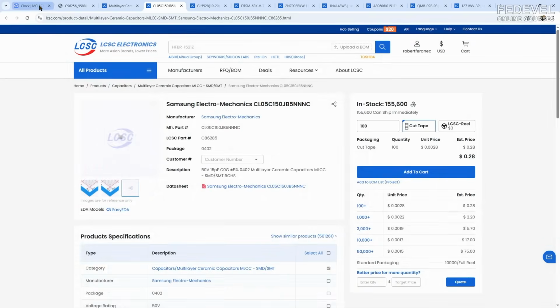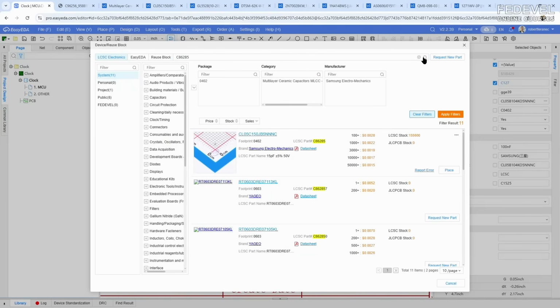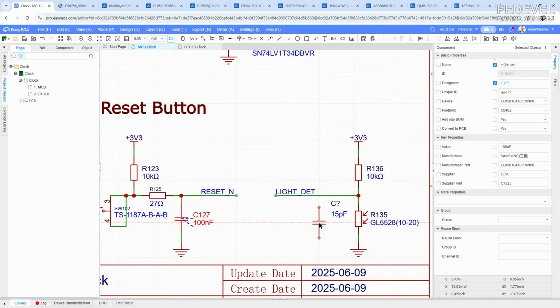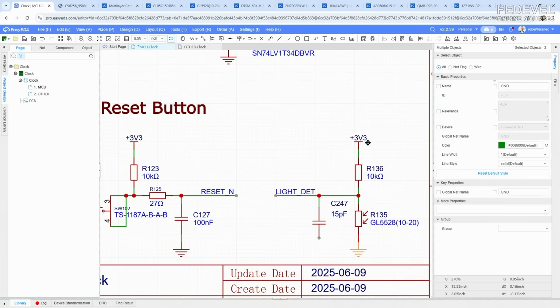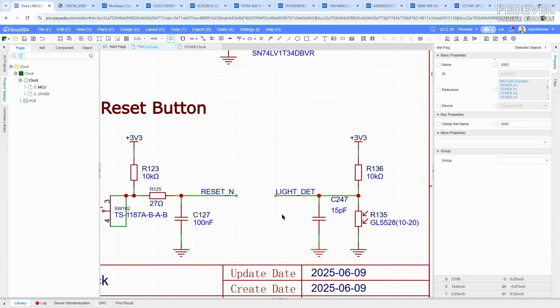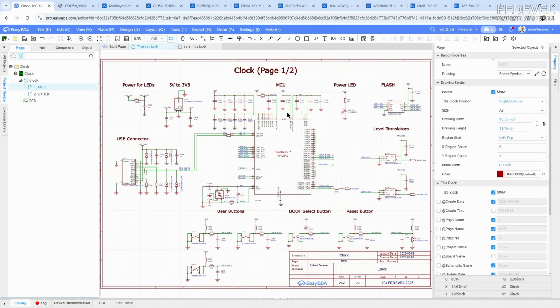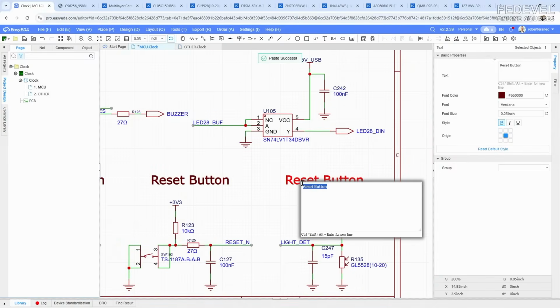Again, this is just basically space for a capacitor. If there are problems with this sensor, you can always adjust the size of the capacitor. It's important to have the footprint there, in case you need the capacitor, then you have the option to fit it there. What is the exact value right now? It's not very important. Make it nice. And of course add this text so everyone knows this is light sensor.